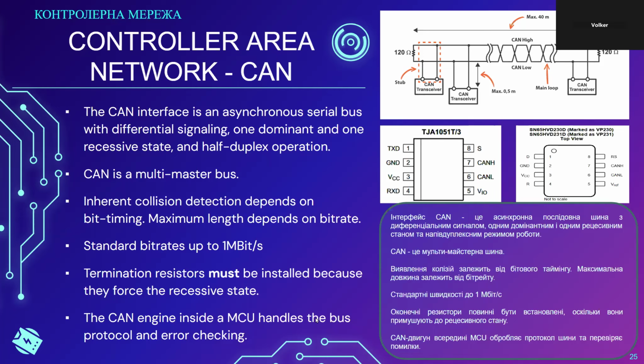You will see in the picture on the upper right-hand side that the CAN bus is intended to have 120 ohm termination resistors. On many buses, termination resistors are required to avoid bus reflections. The reason for this is transmission line theory, which I'm not getting into in this presentation.